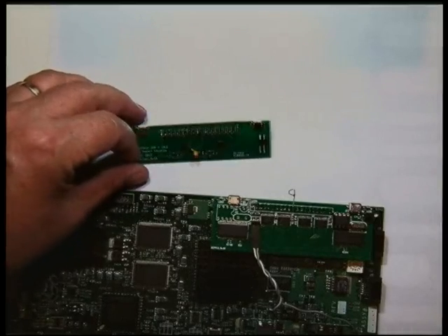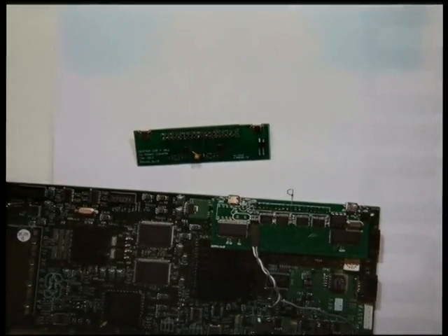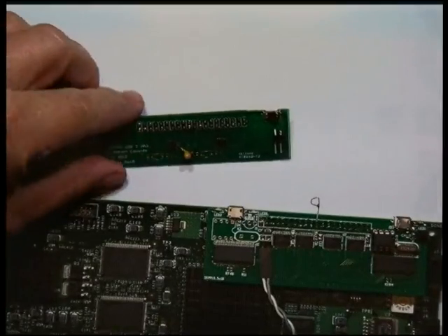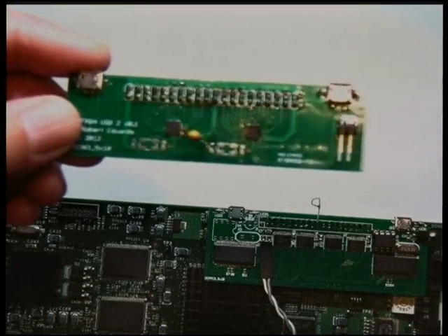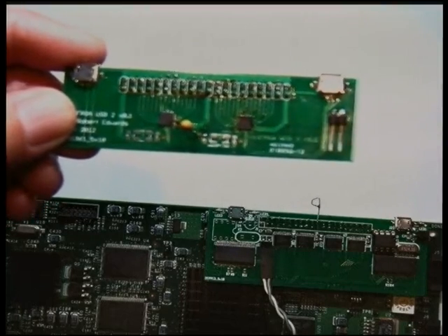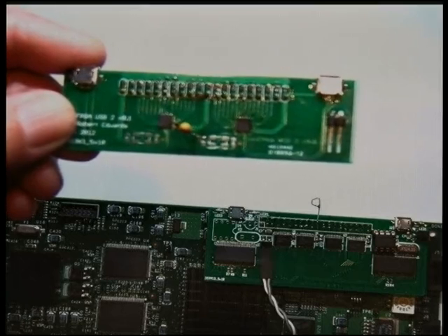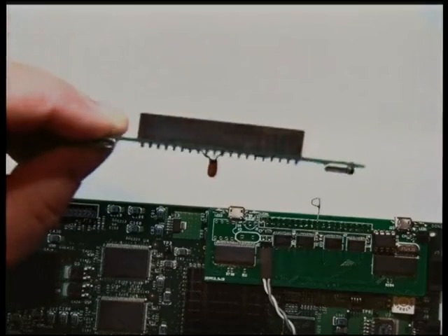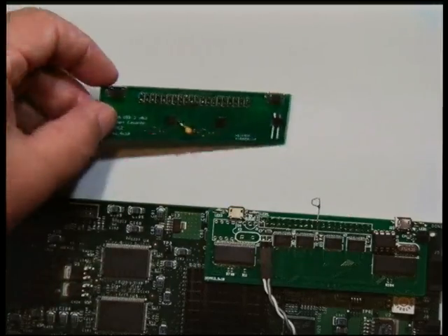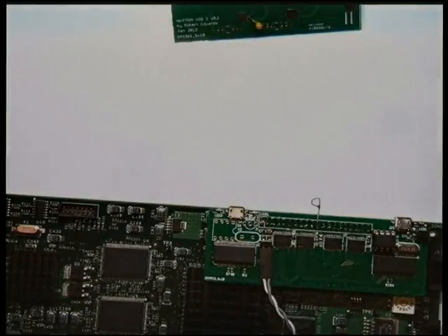So this is the version 0.1 board, and I'll zoom closer in on that. So anyway, it's got those 2 little tiny surface mount chips there, which we soldered with a hot air gun. All the pins are underneath them. There's no pins, they're just ball grid type things, and the debug connector and the 2 USB interfaces. And I think Bunny touched on the problems with this during his talk.